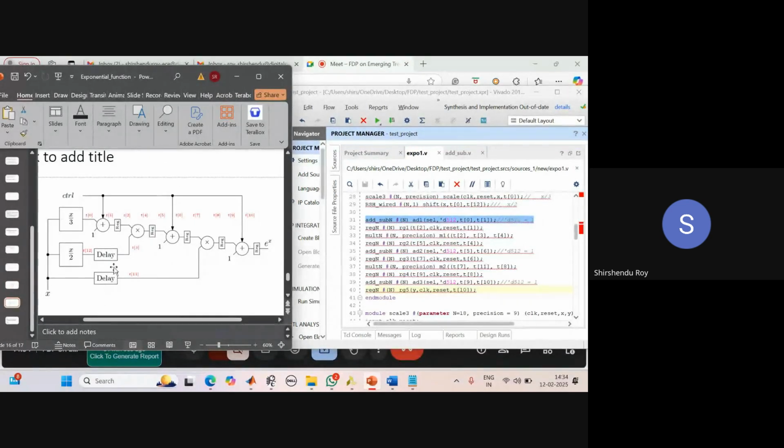And also, there is a register placed between this multiplier and this adder. The total delay, as you can see, is 3. So I have to send this x by 2 only after 3 clock cycles of delay. It is mandatory. If you do not send it, then we'll get the wrong answer. It's called pipelining.